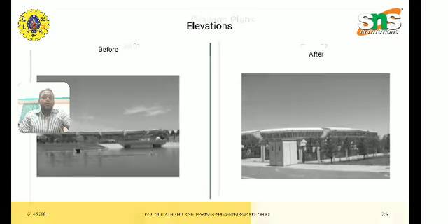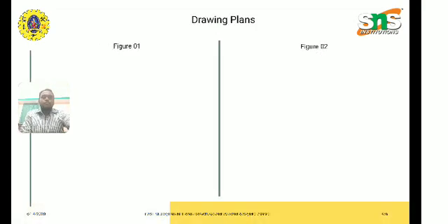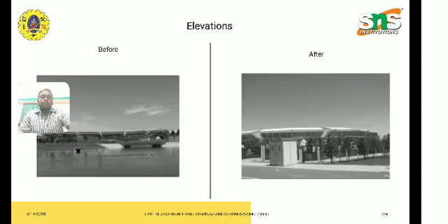Based on that, CAD software is currently applied at colleges and universities to teach drawing. The examples in this project were drawn using AutoCAD. The drawing size must be in line with the design specifications, and the drawing frame should be rendered according to the standard drawing specifications. If creating drawings using a CAD system, the specifications of various organizations vary, and the drawing boundary may or may not be marked, but the frames must be clearly marked with thick lines.